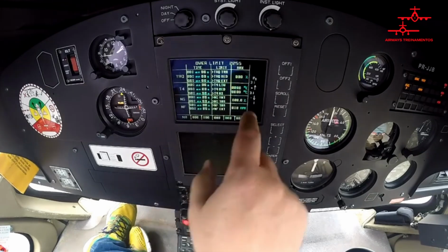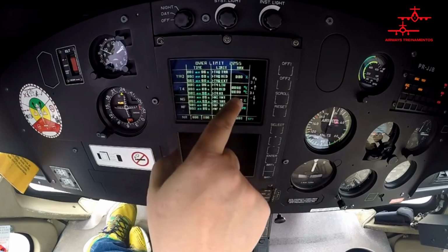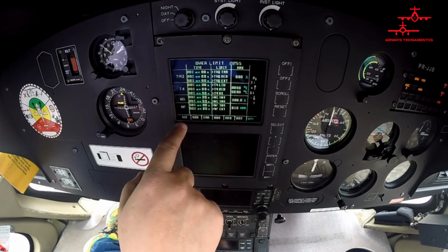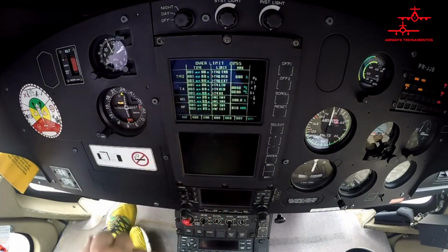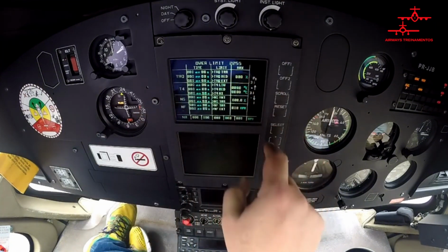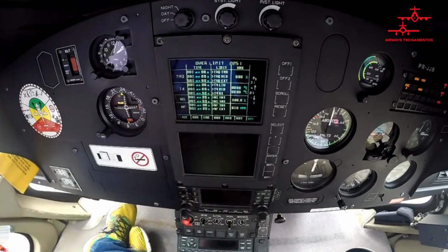So here I have 31 pages that tell me. So if you notice, all the overlimits are here, but there was nothing. Everything is at 0. It checks the overlimits for NR, DNF, DNG, T4, and touch. For me to select these 31 pages, I keep pressing here, right? Okay. There was no fault, so that means if the pilot says, look, I think I did